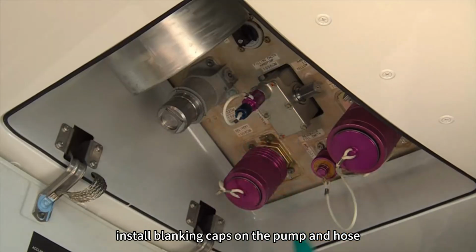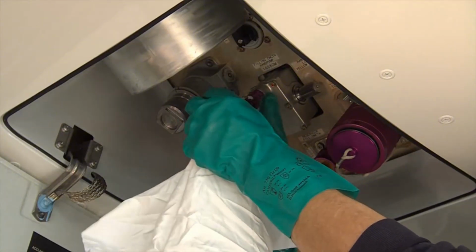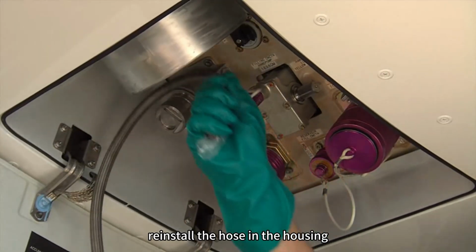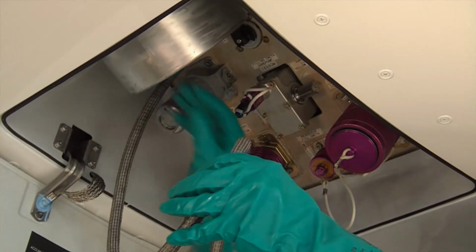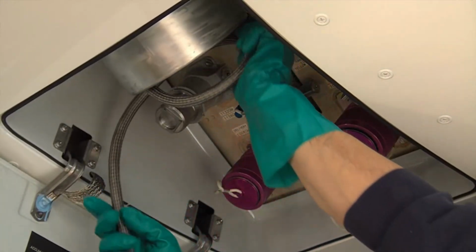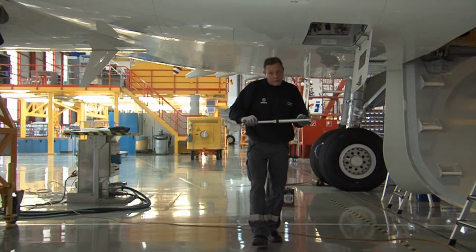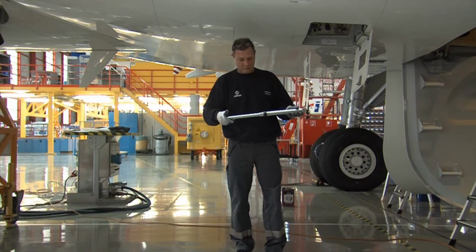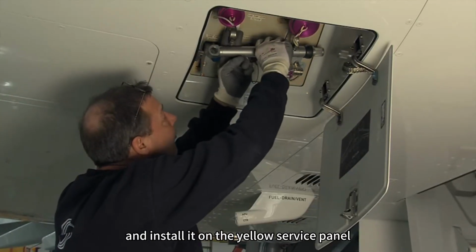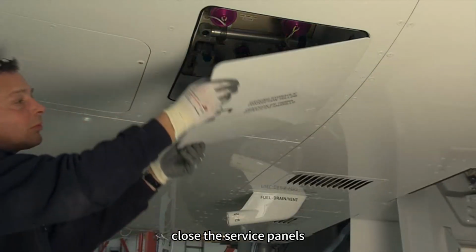Install blanking caps on the pump and hose. Reinstall the hose in the housing. Remove the hand pump lever and reassemble it in its stowing configuration and install it on the yellow service panel. Close the service panels.